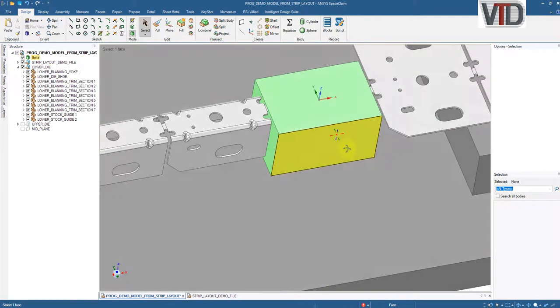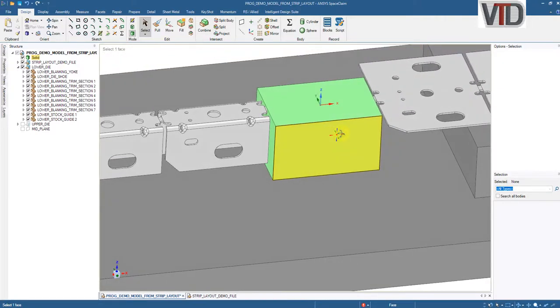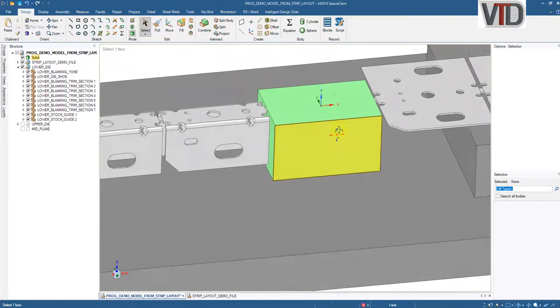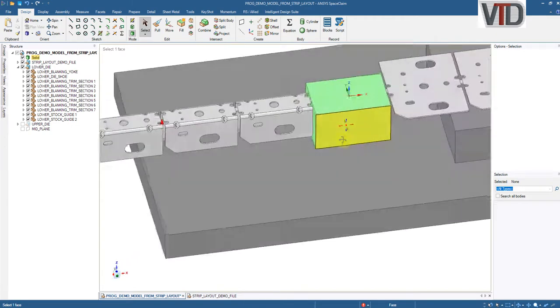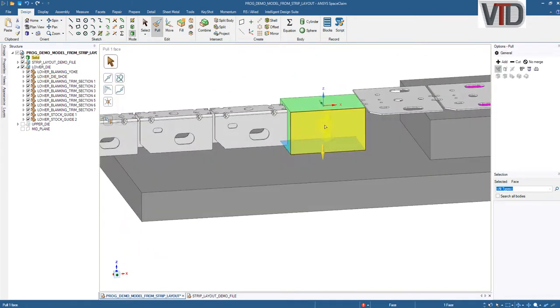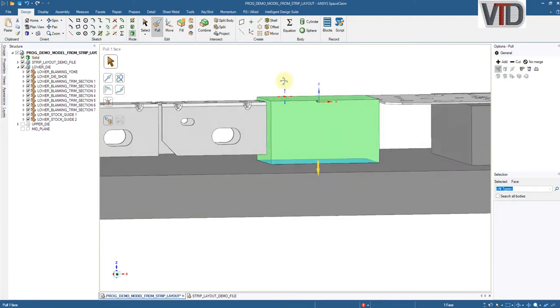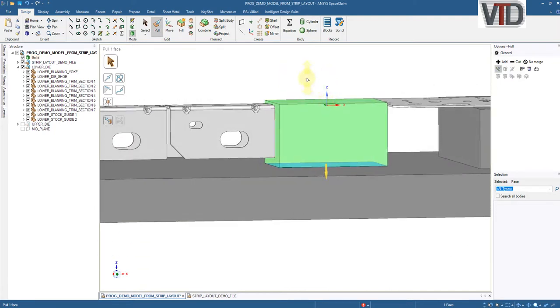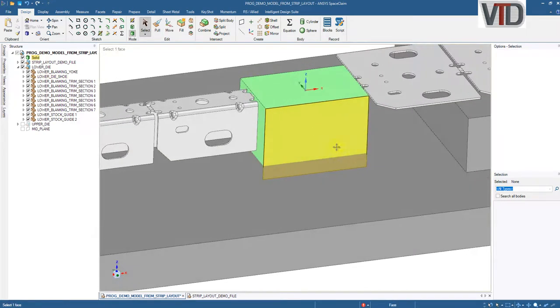So we need to decide, are we going to just have this part stay between the flanges, or are we going to pocket into the shoe? I'm going to go ahead and pocket this into the shoe just to show you that option. During design reviews, you could end up having to change it, but that's the best part about this software, is it's easy to change things. We're going to go ahead and just go 1 inch deeper down into there.